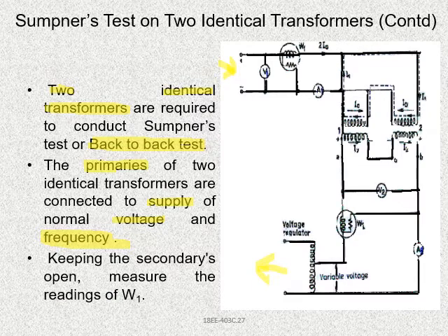Keeping the secondaries open, measure the readings of W1. Keeping the secondaries open and measure the readings of W1. First step: we need to keep the secondaries open and measure W1. W1 is over here.